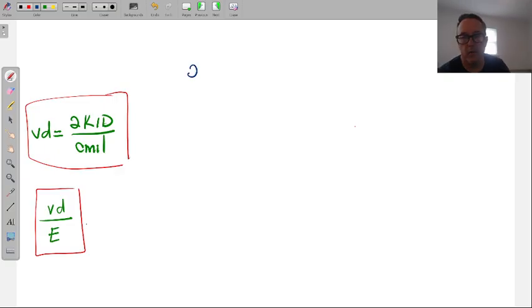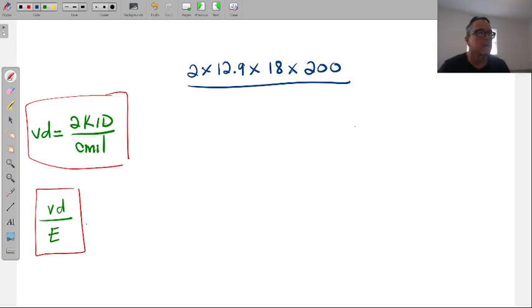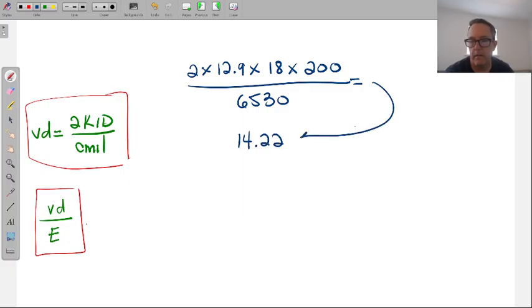So yes, single phase, so we're looking at 2 times 12.9 times the amperage, which is 18, and my footage is 200, divided by 6530. And then we'll have a number there. What do you guys got? 14.22. All right, 14.22. I'll put it down here.